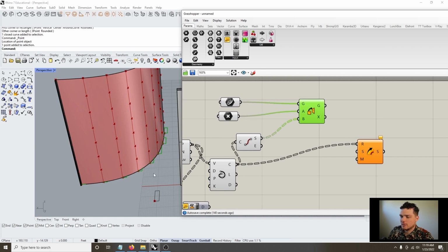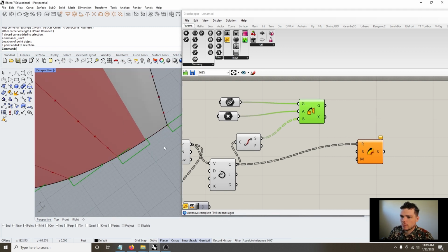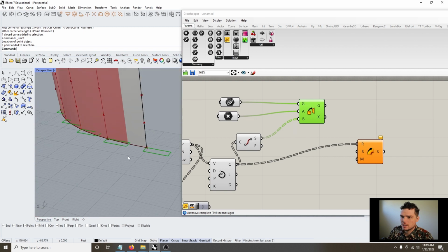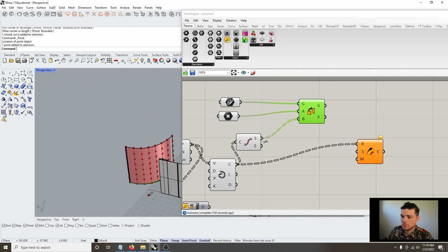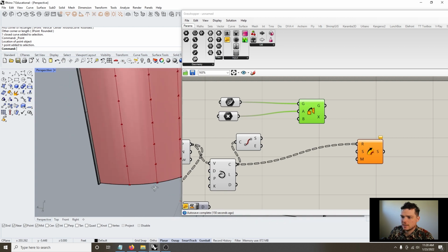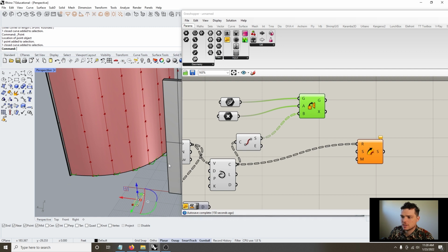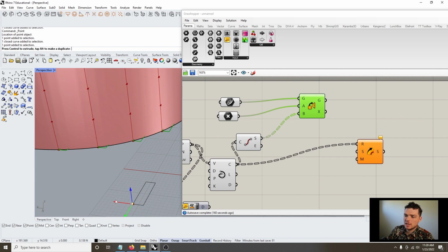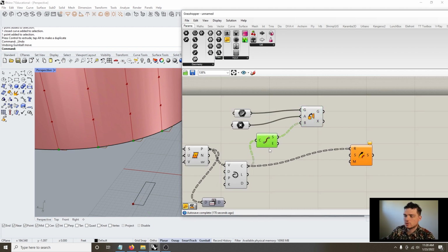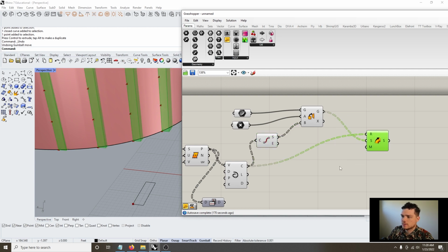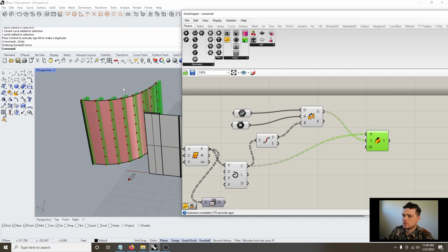Now we have our geometry, and you'll notice that it's already oriented along those points. So pretty cool. Before we did that, it had nothing to orient this geometry to. We type in those sections, and you can already see that this curve is referencing along the geometry. And you'll notice if I move this point, it's going to move the reference to the point. So that's kind of just bounding it to where it needs to be. Then we can take that geometry and extrude it. So it's just extruding it between those two points.